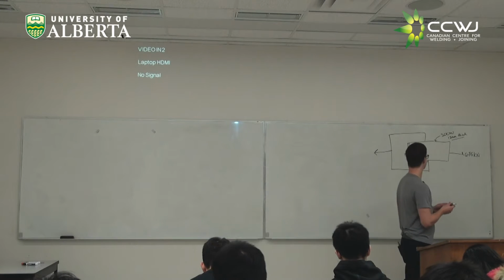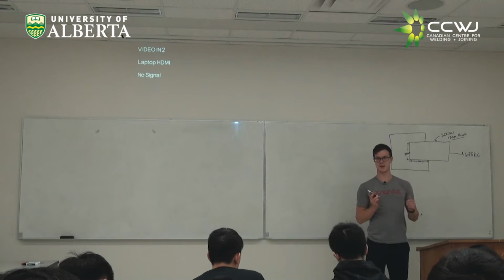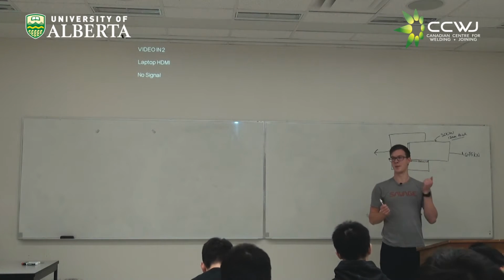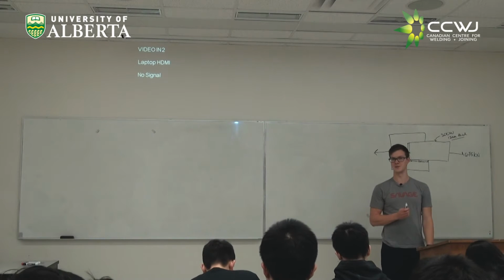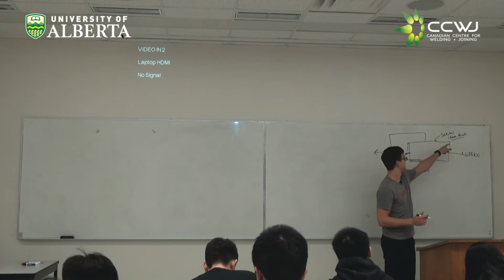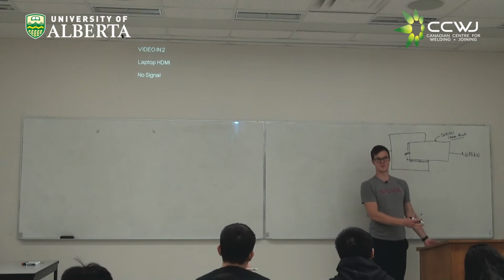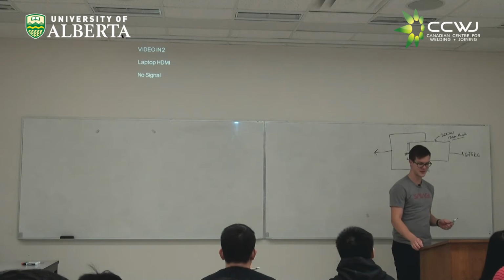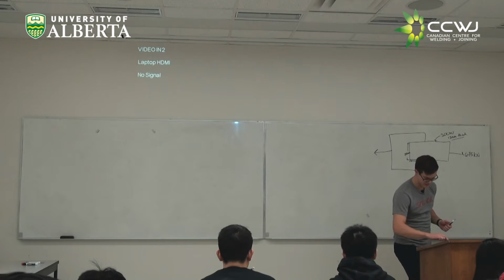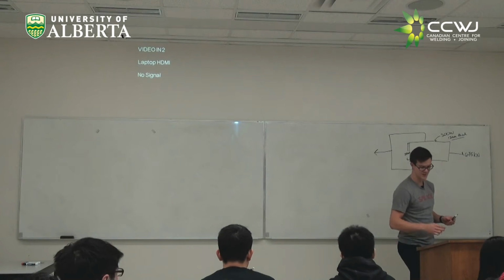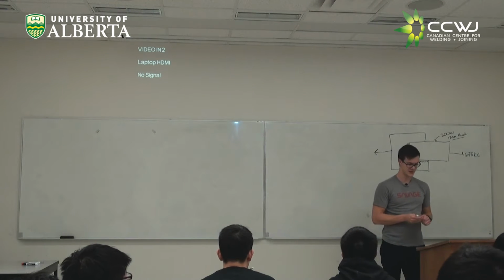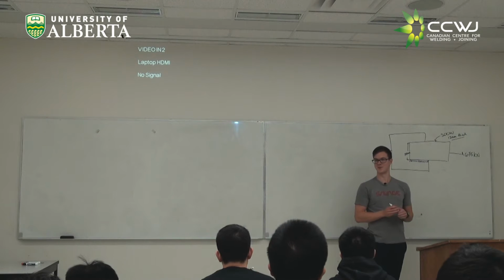So the first part of this we're not going to worry about doing up here. If you guys have the example, you'll see the first part. This was from a previous exam. And the question was, what are the minimum and maximum leg sizes according to the Canadian Institute of Steel Construction? Hopefully you know the only thing you need to solve that is the thickness of your plate. You can go into those requirements, figure out that for a 12 millimeter plate, your minimum is going to tell you you should have at least a 5 millimeter leg size, and the maximum is going to be, anyone remember?